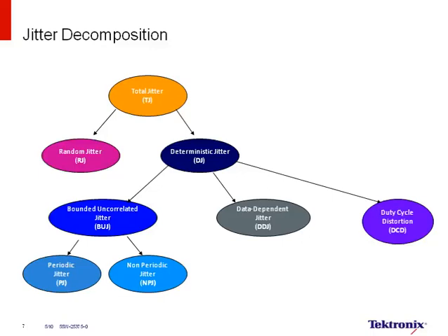When you say you are using the scope, what this means is you are making some kind of a transmitter type measurement, number one, and then when you look at all these different parameters, like the silicon PLL, the CDR loop, you're trying to make the scope behave like a receiver.